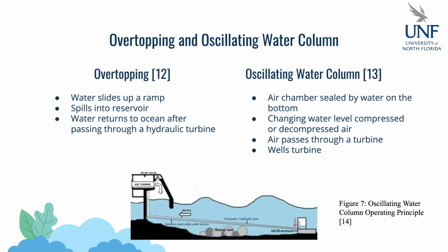And then as waves approach the bowl, it moves the water under the bowl up and down, and it compresses and decompresses the air that's been trapped under the bowl. Same principle with the oscillating water column, except on a larger scale. And the way we capture the energy is that air that's trapped under the bowl. What we do is we force it through a channel, and in that channel, we have an air turbine.